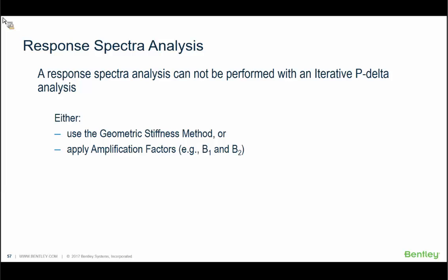Response spectra analysis is not an iterative analysis, and so you can't be doing both a response spectra analysis and an iterative P-delta analysis simultaneously to have the effects combined into the final results. As a result, the P-delta effects are often neglected. People run the response spectra analysis and don't realize they're not getting any of those P-delta effects included.